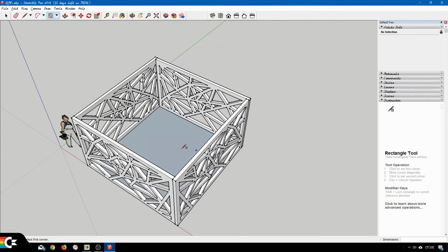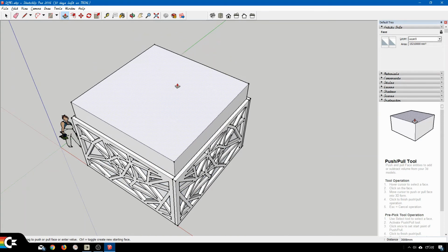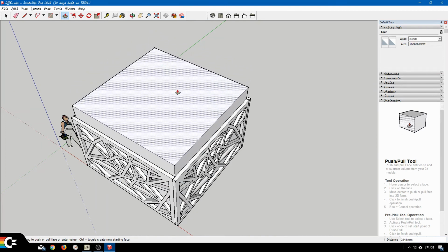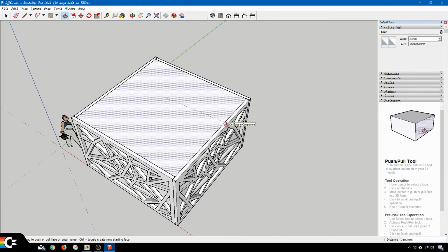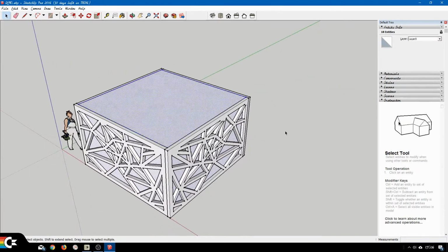Okay, we're almost done. I'm going to get my push-pull tool. Tap that surface. You can see the blue dots mean it's going to extrude that surface. Tap it once. And now I'm going to move it up, and if you remember the height of the wall was 2400, I could type that in, or I could simply touch that surface and click my mouse the final time. So now it's up exactly the right height, and now I can use my selection tool, triple click it, that selected the entire cuboid, and not the walls which have been grouped.